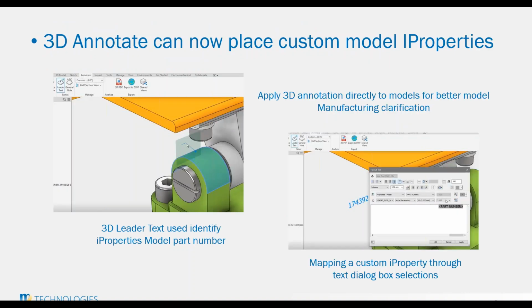And this is the 3D Annotate tool. In the past, it did not allow you to tag custom model property information. What it will allow you to do is very much like the 2D leader tool that you would see in the drawing information area. It's pretty much the same. You attach the leader to a surface or a face, wherever it may be, and then from the leader note information, you can start to drop in parameters from the back end. You can tie in this model information that will basically allow you to be exported.